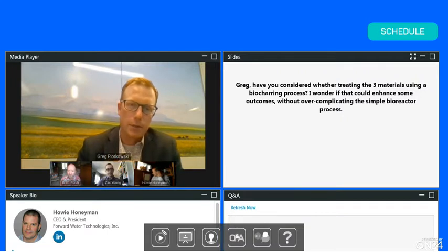So you transition from a biological process to basically a physical chemical process. It's more of a sorption-based system. Biochar in and of itself is a really good sorbent for more organic chemicals, but they can be modified to have a charge, so then they could hold on to inorganic nutrients. But for the sake of simplicity for a lot of soil water conservation practices, having a biological system with relatively fresh residue that they could pull off their field and put into a trench is probably the preferred way to go in this iteration anyway, because it is a lot simpler and more direct.